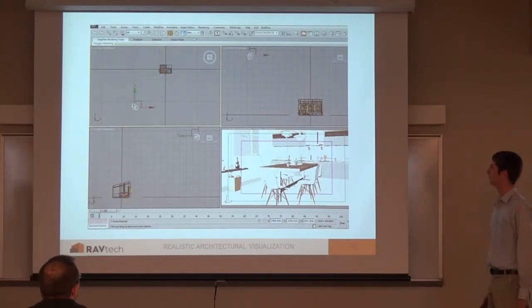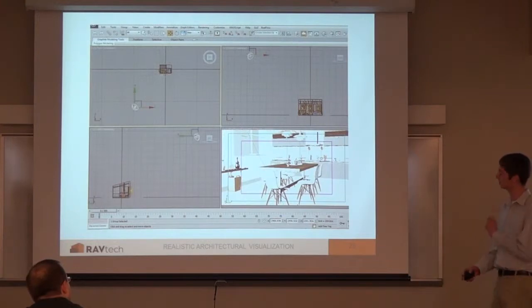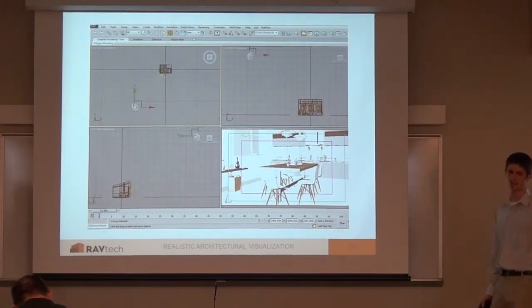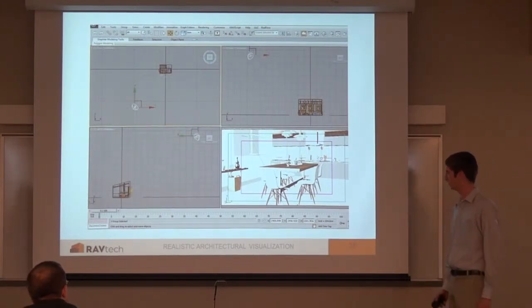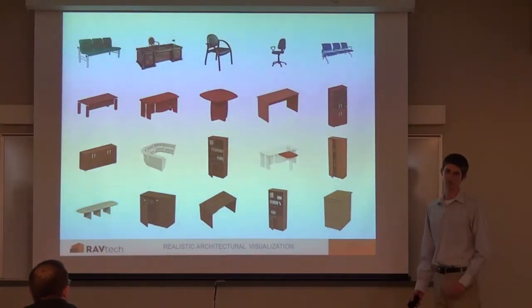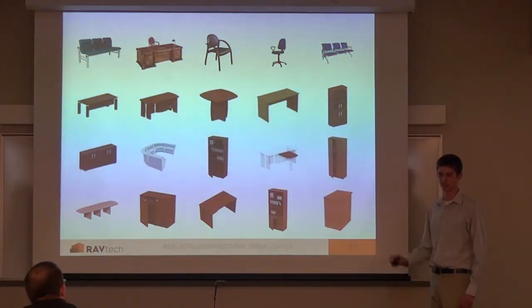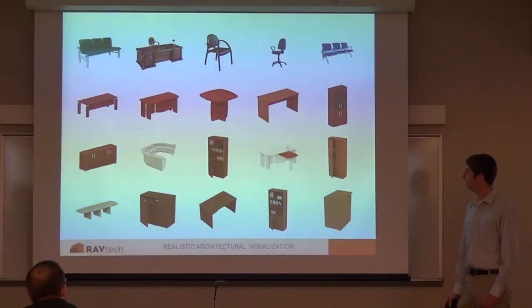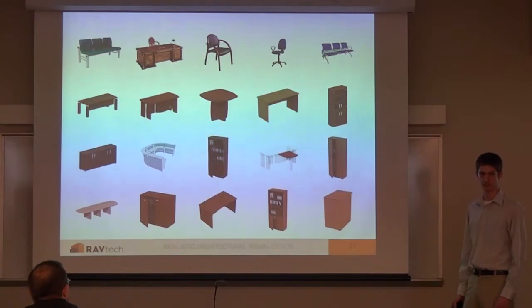That doesn't, if you're doing man-made lights inside it, you can change so much stuff with that. I mean, what kind of light are you putting in, what filter color, and you can get into that, but for starting out, it's best to just go with one light source. As I said, with the Revit furniture being awful, you can find thousands of free furniture models online, and they will just make your scene look so much better.